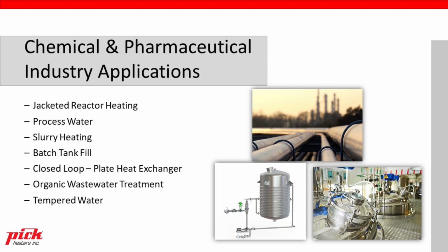So we do provide data sheets with each application. I ask you to fill out data sheets, and it's engineered by the rep or the factory, and information is sent on that particular recommendation. Also, organic wastewater treatment is a common application in this industry, and in many industries as it is. And then in chemical and pharmaceutical, they sometimes just need tempered water. So steam injection heating is a great piece of equipment for that tempered water heating.